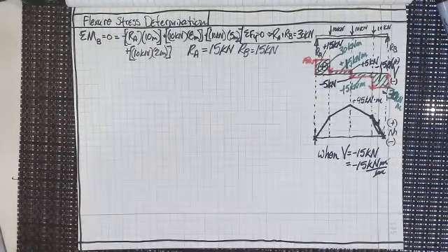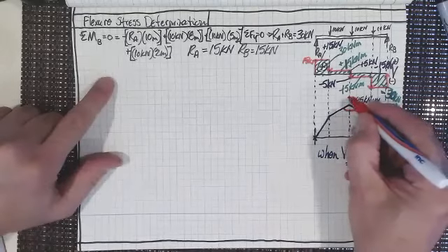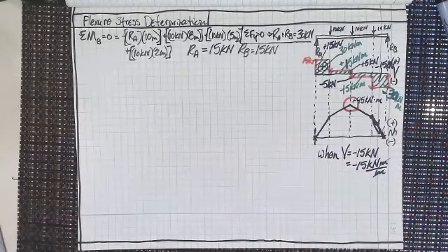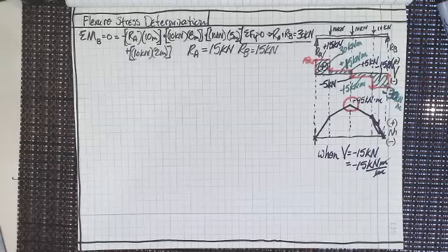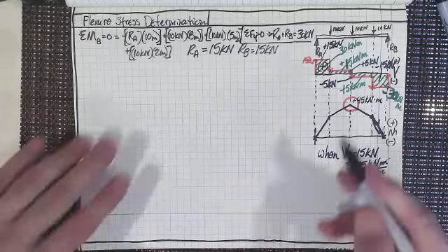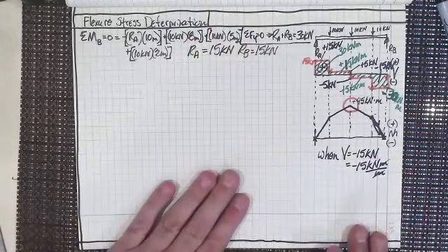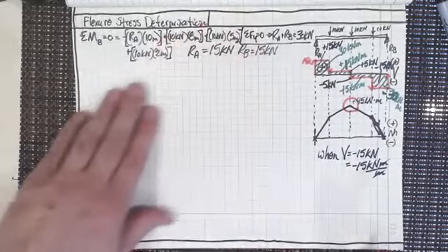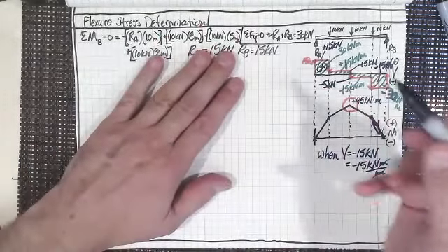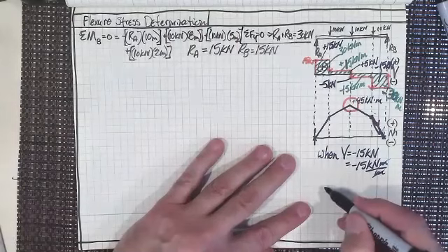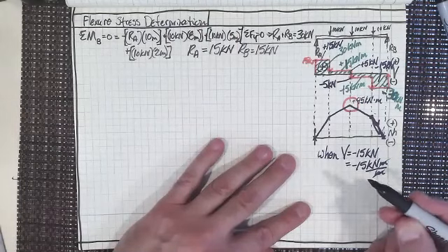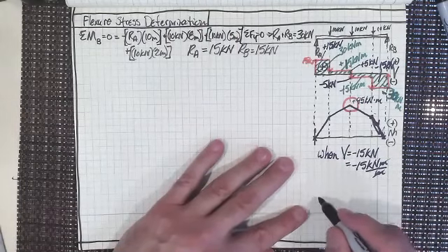All right, so what we're looking at right now is a maximum, right? What's our maximum bending moment? Right there, 45 kilonewton meters. So we want to see if this cross-sectional beam works, and I haven't gotten to that yet, but I'm going to do that right now. So I'm going to look at an I-beam, and I'll draw it right here. Wow, that looks like a really, where did I get that one?